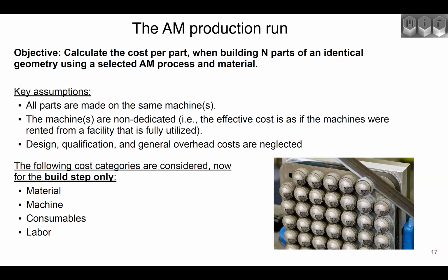And again, going back to the fixed versus variable cost discussion, if a machine is dedicated, meaning it's only making one type of part, and you don't have sufficient demand to utilize that capacity, so if your machine is running at 50% of its available capacity, you still are paying the annual cost of that machine fully on that 50% capacity, meaning that the cost of the machine is twice what it could be if the machine were being used at 100% capacity.